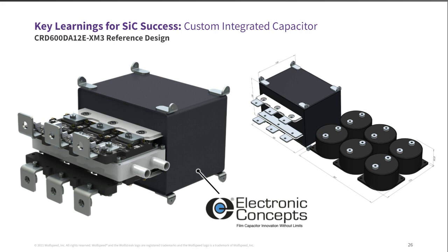moving from the 300 kilowatt kits with 300 microfarad capacitors, if we were to double that to 600 microfarad capacitors, the form factor is not quite there, and how you would have to mount the capacitors and bring the busing out to then try to get a symmetrical connection to both sides of the power modules would be difficult.